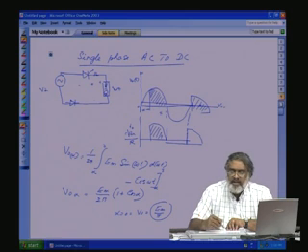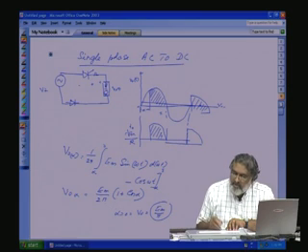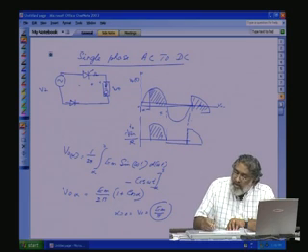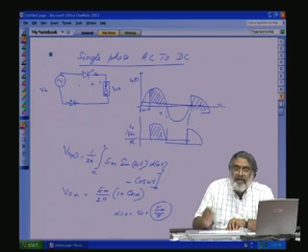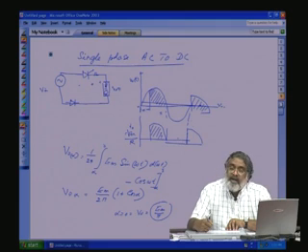So, even though these types of AC to DC converters using diodes or thyristors are available in the textbook, this is only for understanding how to get the DC value. So, this value we talked about is the DC value. But along with this value, because of this variation, you will have the ripple content also. That ripple voltage will produce its own ripple current, that has to be suppressed by the load. But we will not be putting any extra filters to suppress this.